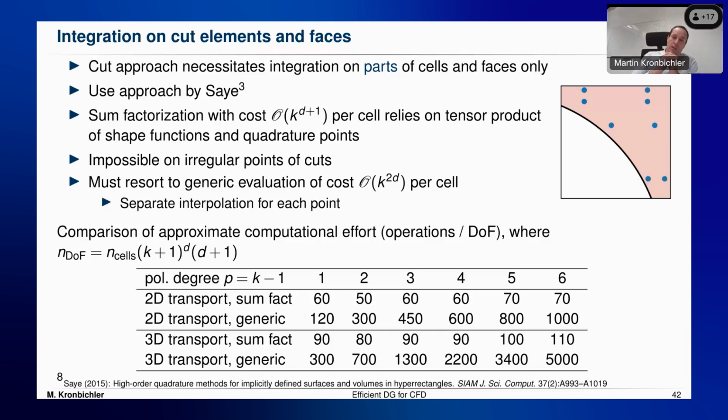And in that case, maybe it's a factor of 3 to 5 slower per unknown than the hexahedral elements, which, I mean, it sounds like quite a lot, but on the other hand, you can use arbitrary meshes. And if you do a hex mesh with a bad element quality, then your CFL condition is much more reduced than a factor of 3. So in that sense, I would say it's not too bad. At least that's our experience.